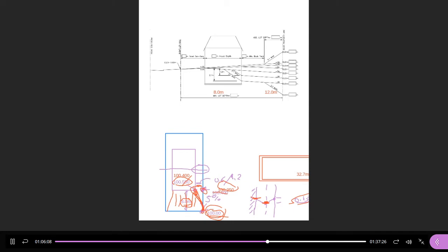Okay, Daniel and Claire, I think you're off there. Let's do it again. If you have to do the calculation in two parts, you can. So what's the elevation at the back of the building? The elevation here is going to be 20 times 0.02 is 0.4, 0.40, positive. So that's the elevation at the back.